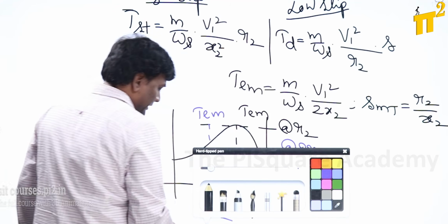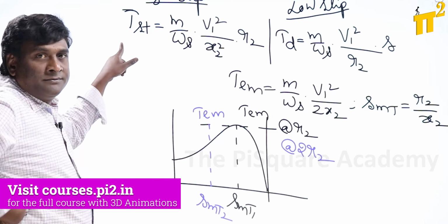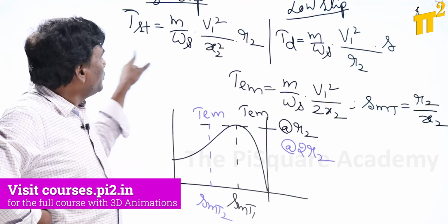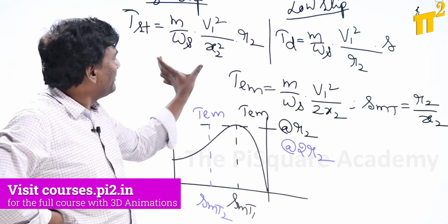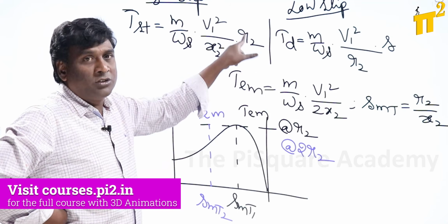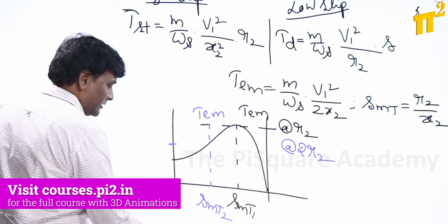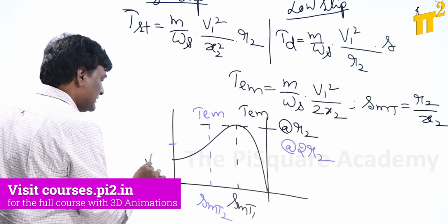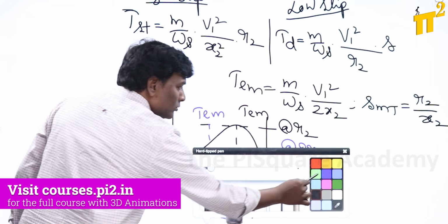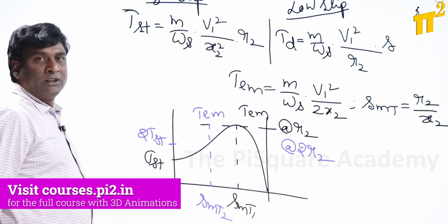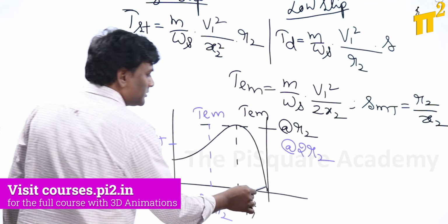Now next thing is, let us think of starting torque. Okay, because starting torque and pull out torque will be decided by machine. So for example, R2 is doubled. Okay, remaining everything is constant, R2 is doubled, then starting torque is going to be doubled. Okay, so previously this is starting torque for the black, now this is going to be 2 times TST. Now draw the characteristics.